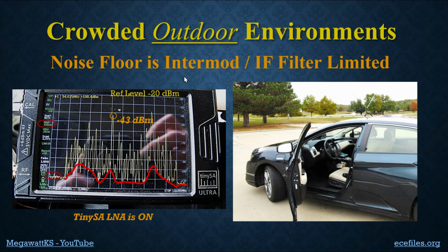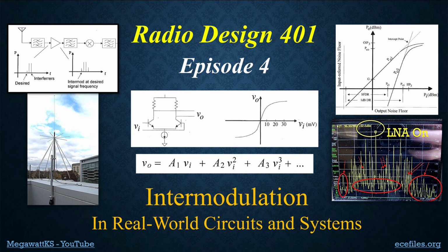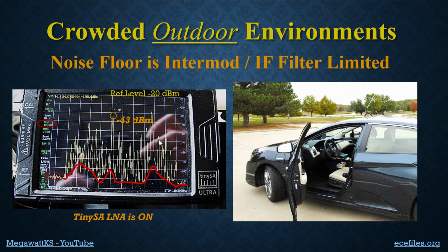Well, it's probably due largely to intermods, which is what we discussed in great detail in episode 4. So if you're interested in that, have a look at episode 4 sometime. But I think we're also being limited in this particular spectrum analyzer trace by the IF filter being used.